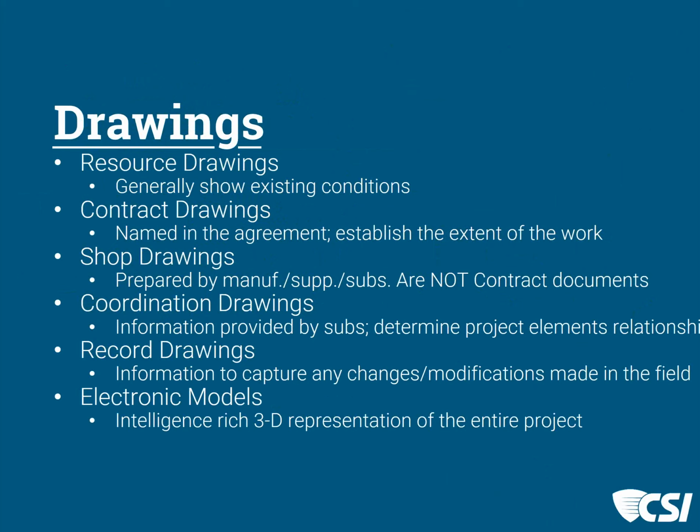There are also shop drawings that are a part of the drawings that are typically prepared by those who will be more closely involved with the work, either manufacturers or suppliers or the subs that are putting up work. But there's an important distinction in those shop drawings, and that is that they are not contract documents. They're supplemental information. They're important. They need to pass through your office under a critical eye, but they are not a part of the contract documents.